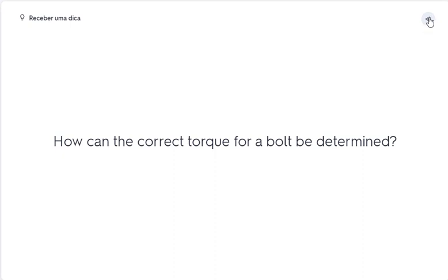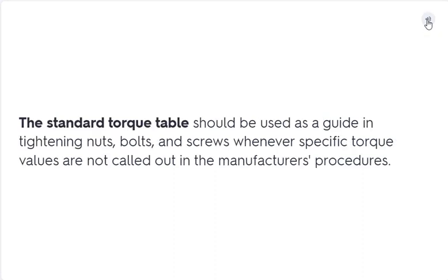How can the correct torque for a bolt be determined? The standard torque table should be used as a guide in tightening nuts, bolts, and screws whenever specific torque values are not called out in the manufacturer's procedures.